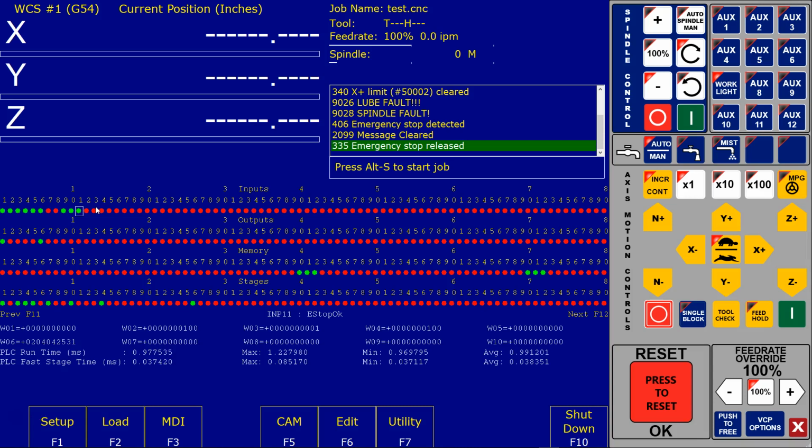Okay. As you saw before, when I clicked on spindle enable, I turned output 7 on. All right. And I just clicked on this and turned it off. But if I wanted to, I can force an output just by taking that white box, scrolling over to that particular output, and now I'm going to hit Control, Alt, and F for forcing. As you can see, that circle changed from red to green, and there's a white line below that particular output. That white line tells the controller that that output has been in a forced state.